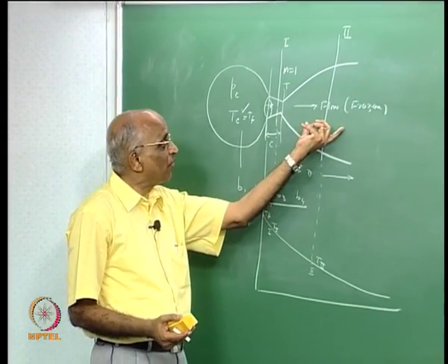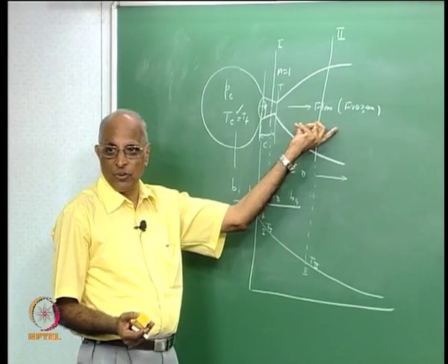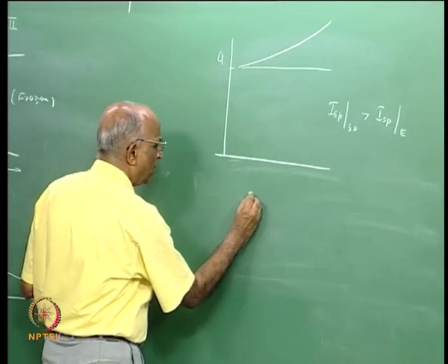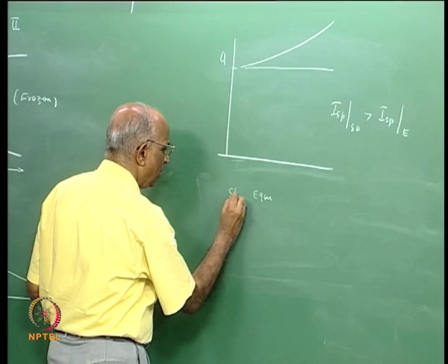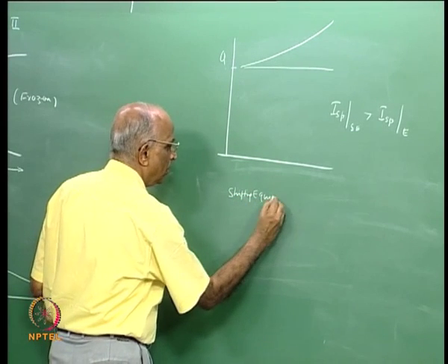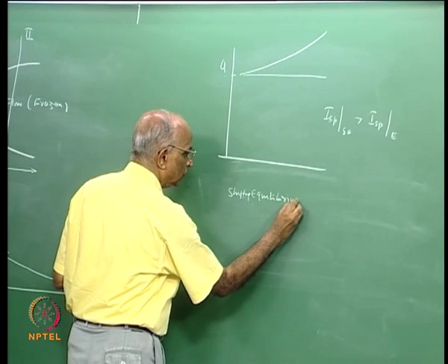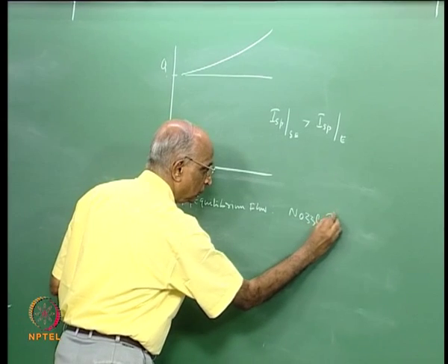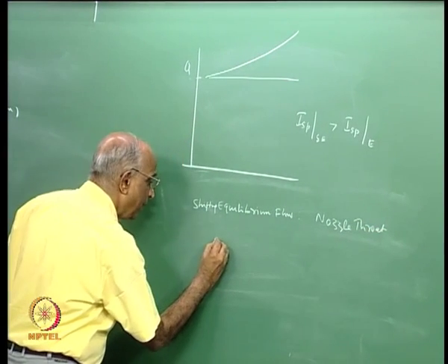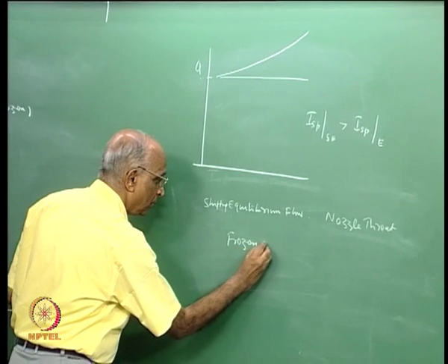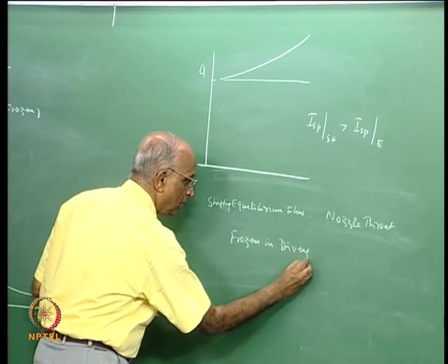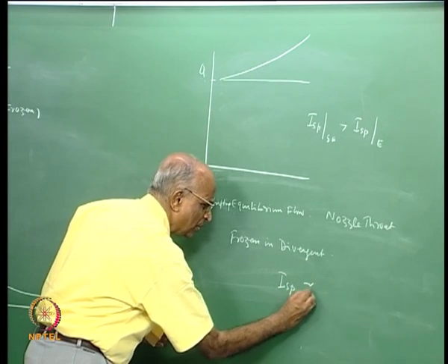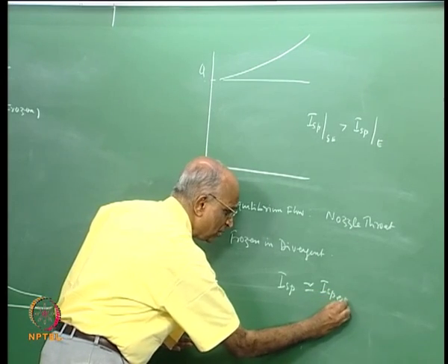In my divergent, where the flow is supersonic, there may not be time for equilibrium to take place, and the general practice we find is, you assume equilibrium flow or shifting equilibrium flow up to the nozzle throat and frozen thereafter, and this seems to give the value of specific impulse near the values which are experimentally measured. But this is not always true.